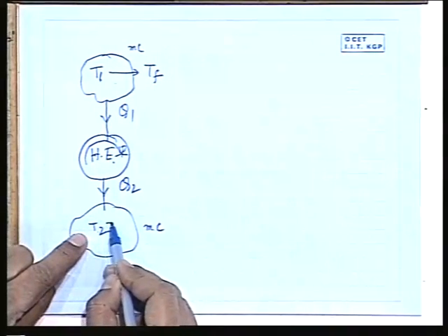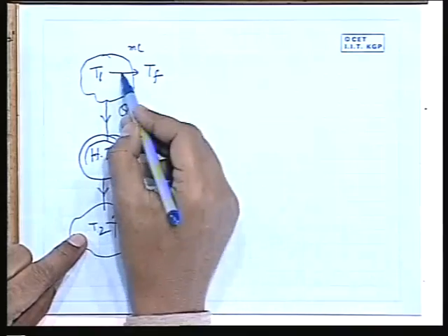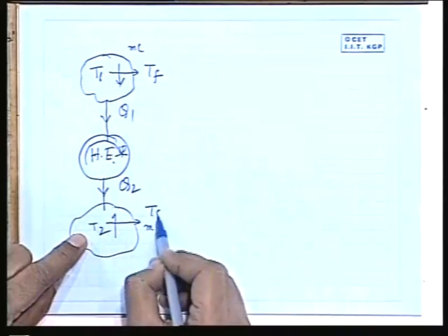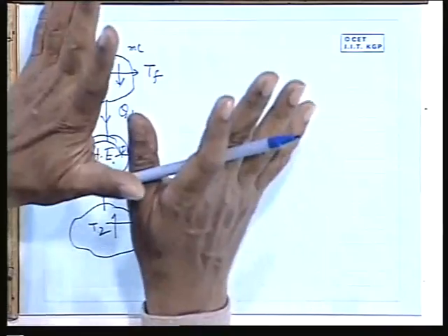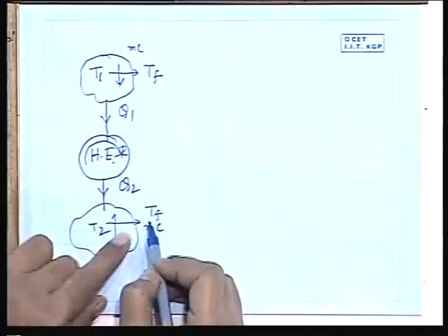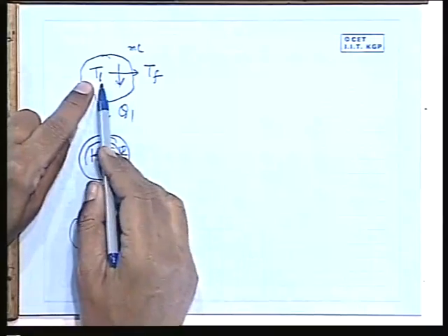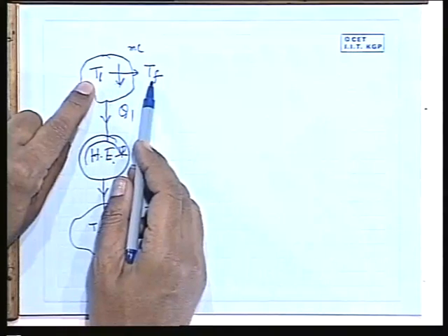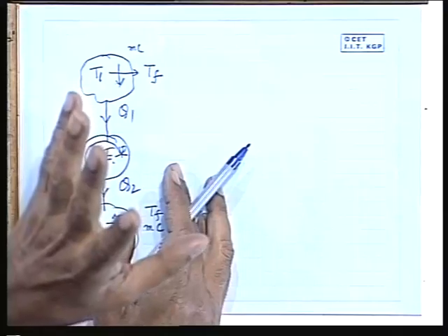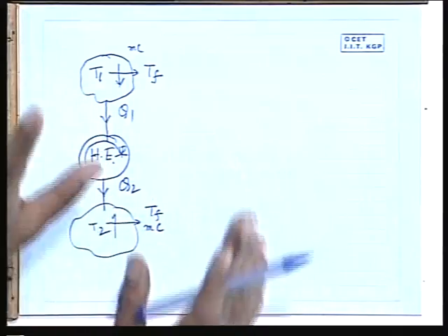Similarly, this temperature is going up, and the engine will automatically stop when there is a common temperature. When the temperature is the same, the engine stops, because according to the second law of thermodynamics, until and unless there is a temperature difference, a heat engine cannot operate. A heat engine cannot deliver work taking heat from a reservoir of single fixed temperature. So there will be a common temperature where it stops, and this variation of temperature from T1 to Tf in finite bodies does not tell us that reversible heat transfer will not be there. We can conceive of a reversible heat transfer with a varying temperature, as I have told earlier.